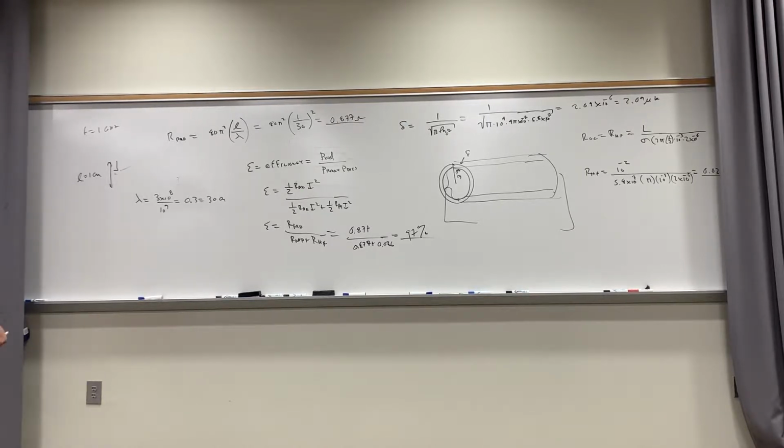Well, the 13.56 megahertz source had piping that was all hollow. And the reason is all the current hugs the surface. So having any metal in the center would just be a waste. So what they did is hollow it out, and they had water run through the center. It was distilled water to cool it, because this is a plasma reactor and it gets hot. That's how they did it, which is interesting.